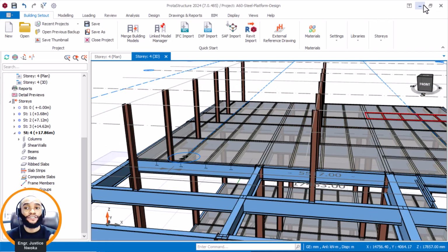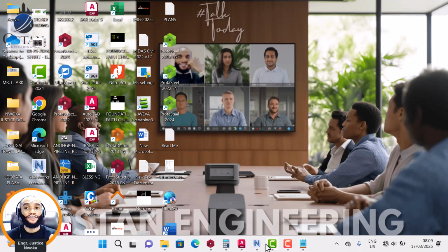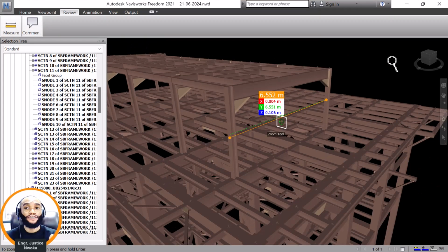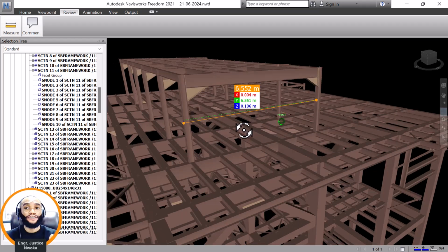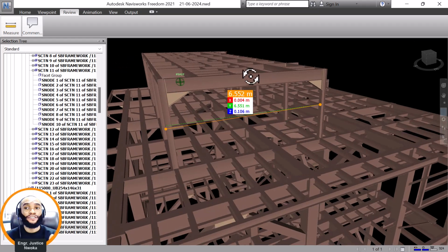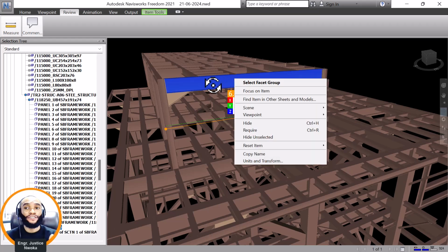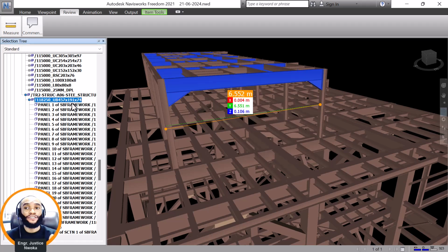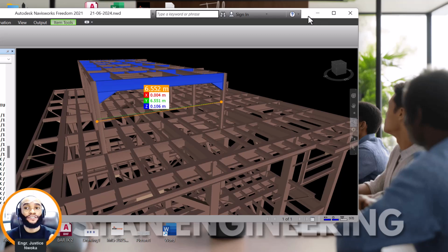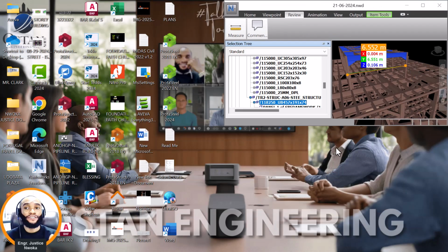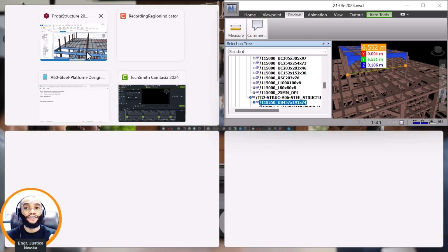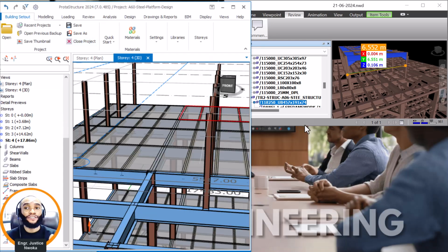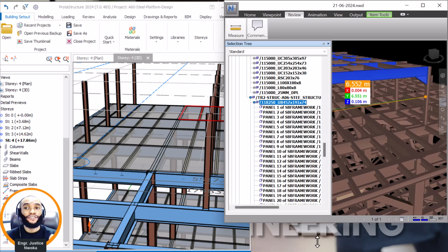Okay, so going back to our Navisworks now, which is our E3D. You can see what we have now. We now have beams running here. This beam here, let's see the size from this place. Now we have UB 457 191 40, yeah, that's fine. So I'll keep this way, just push it this way, that's fine. Keep this here, okay. Then bring this down. Okay, that's fine.